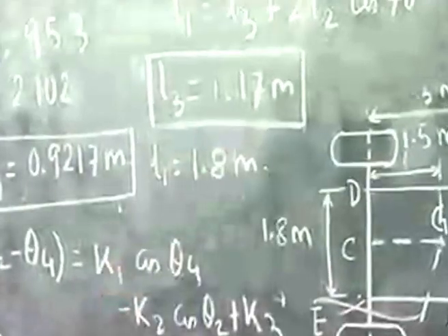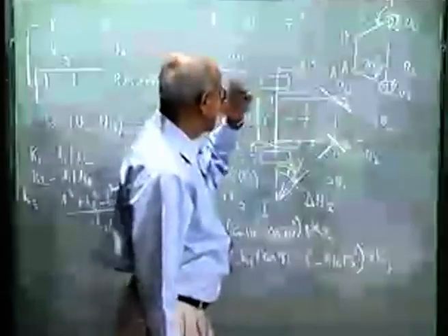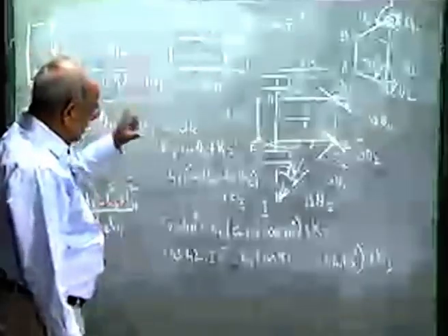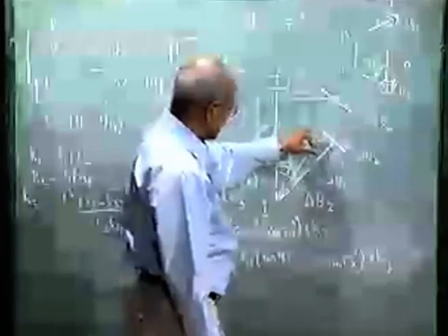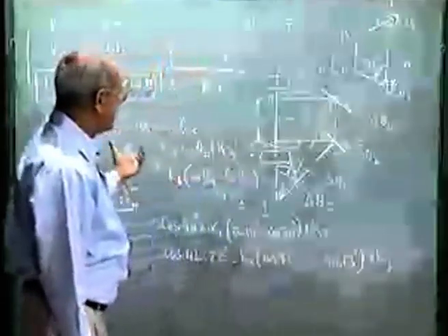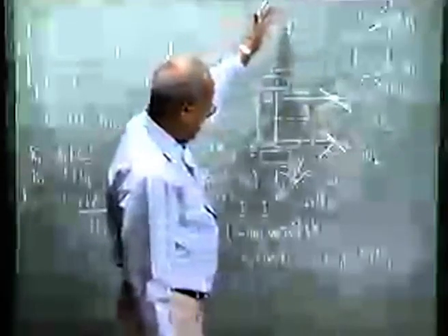So we can use the Pruden method to solve for this, to synthesize this Ackermann steering mechanism to satisfy the requirement that at a particular value of the turning radius for the center point G, which we took as 11.55 meters, the steering condition will be exactly satisfied. It will be exactly satisfied for an identical left-hand turn. This we did for right-hand turn, and obviously it is all right for the straight path.